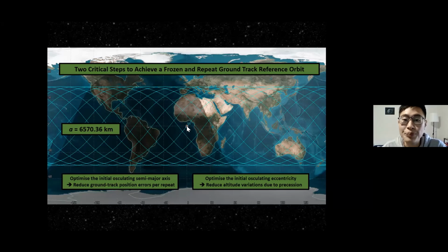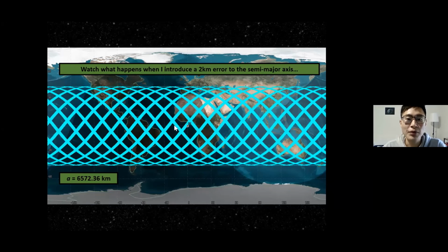And although we always say that the 6 orbit elements are very basic, very simple, what we were optimizing were the 6 orbit elements. In particular, they were the initial orbit elements that you choose when you are launching and inserting. Is there a very specific set of initial elements that minimizes the variations in your latitude, longitude movement, as well as your altitude movement? So there's an optimization.